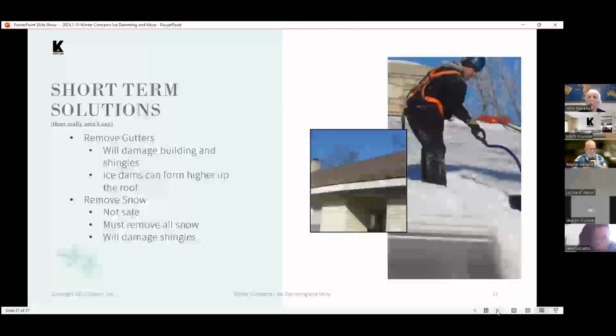It doesn't require a gutter because the same process goes on. So if you've pretty much lost the snow blanket on the roof, but you're still getting the leaking from what's already accumulated, you can pull the gutter off. That'll drain, and you'll not have your problem anymore. But if there's still snow on the upper part of the roof, you're going to get reforming of the ice dams.